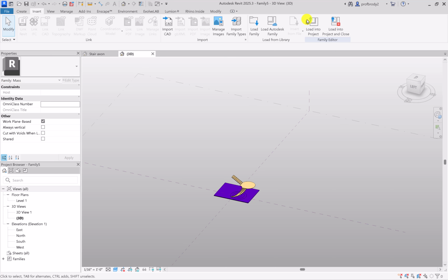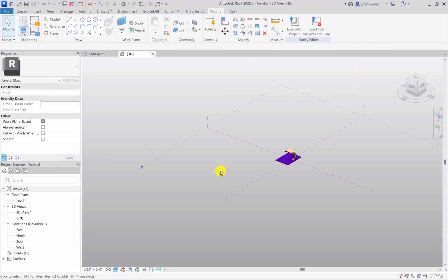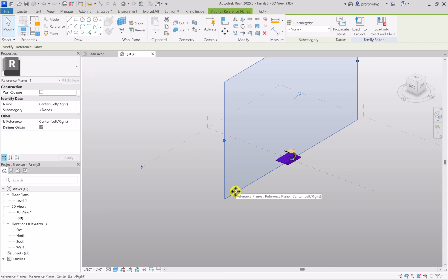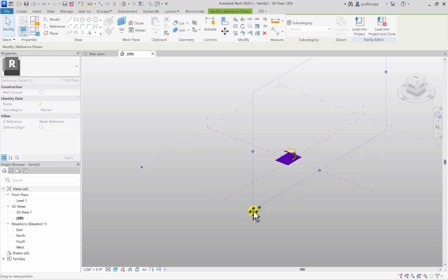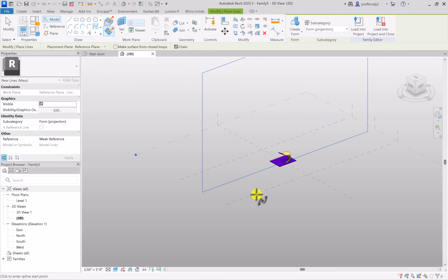You draw profiles any which way you want. They can be completely enclosed, or they can be open like the ones we created already. So big picture, in the conceptual massing environment, you can create really any sort of shape using these reference planes. I'm going to copy them using Control, and this is great if you're, I don't know, working on a roof. And on each of these, you have the freedom to draw easily. So for example, let's say I was creating some kind of funky roof.